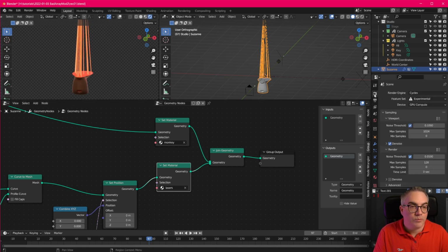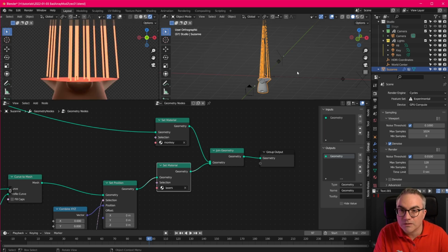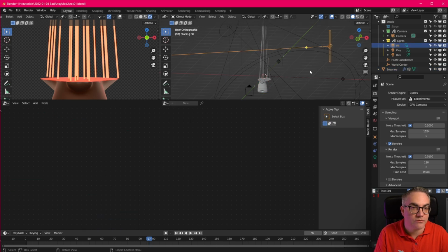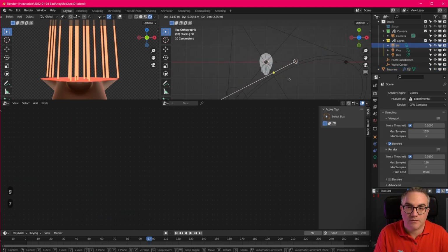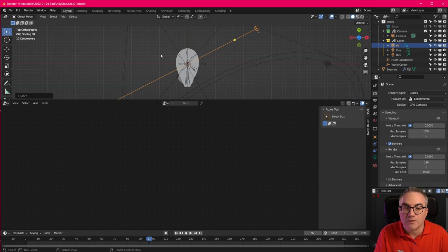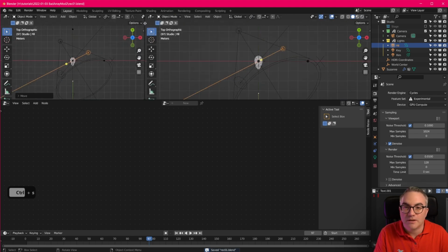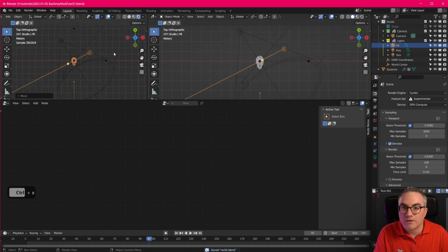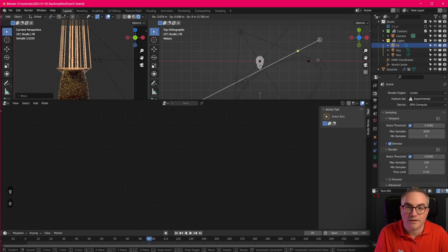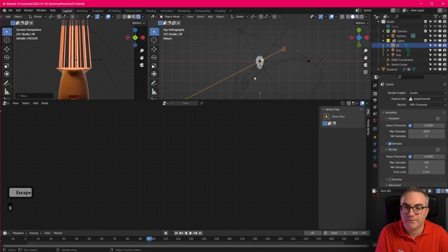Okay, now with the bloom effect in Eevee, you get a nice bloom. In Cycles, you can do this in the post processor. I don't think my lights are still working. Does this look like the lights are working? Let's see. Lights fill. Maybe this doesn't do anything. Okay, once again, let's close this, save the file, open it, go to rendered view. Ah, now we have lights. Yep. Cool, okay.